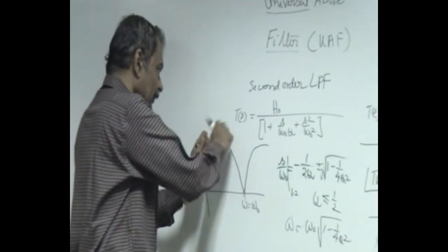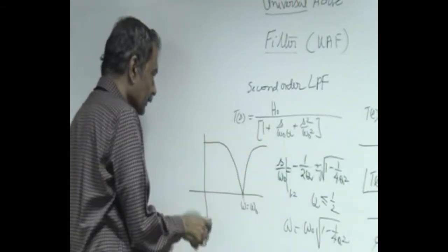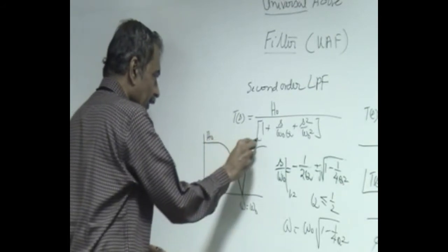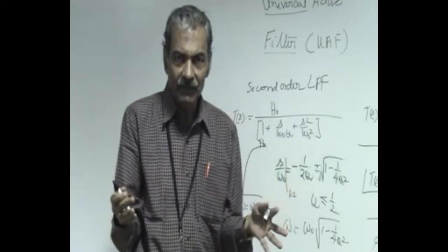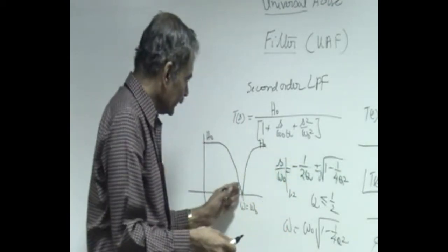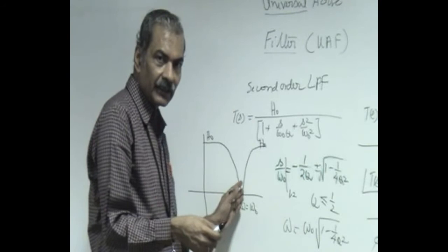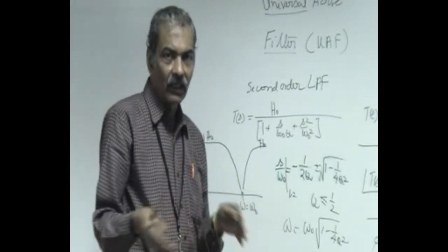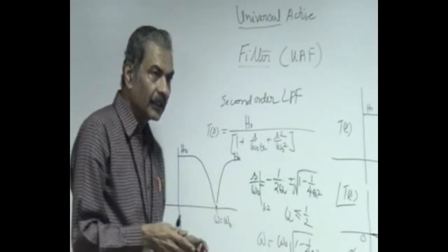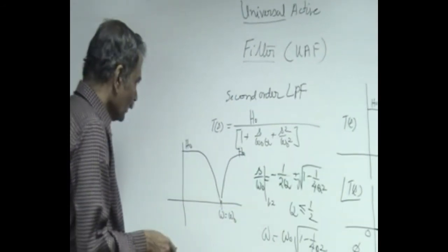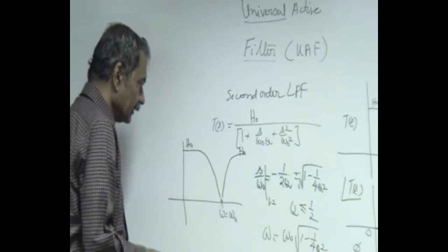The higher the Q, the sharper the notch. Therefore, it can be conveniently used to reject, for example, the 50 Hz power line frequency. So you can reject the unwanted frequency, clock frequency or power line frequency, which is normally the most irritating thing in signals, using a notch filter.